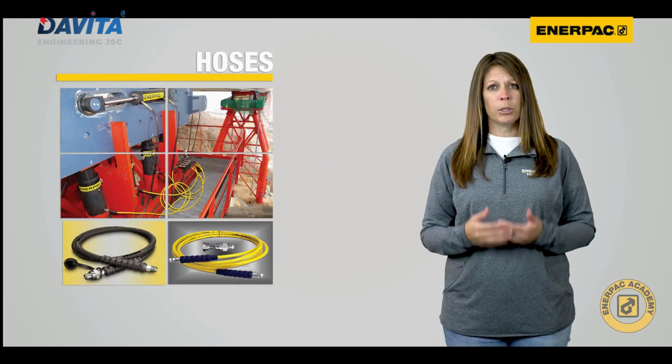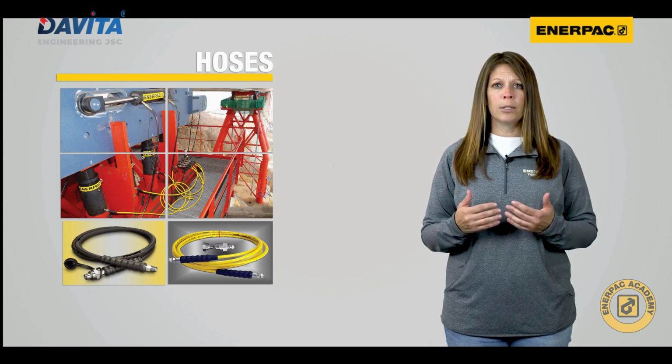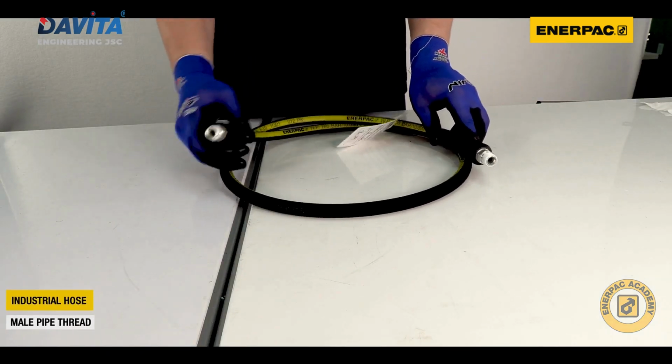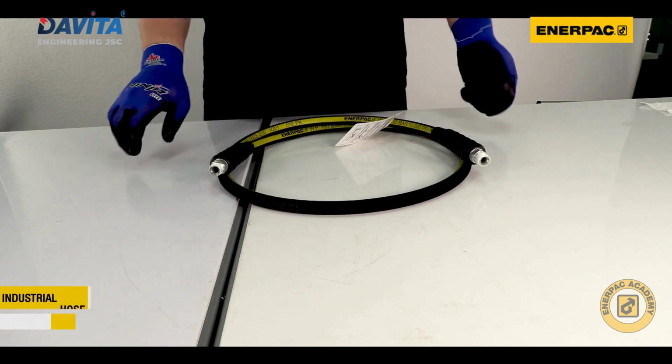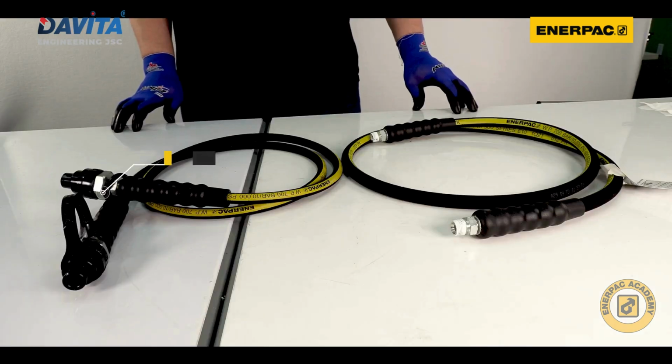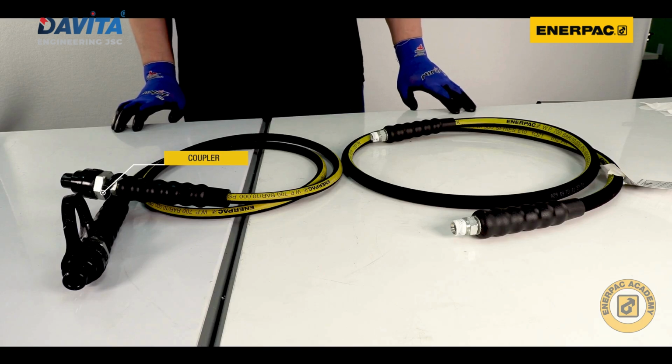The final term to understand is the hose end or end assembly. Most industrial hoses feature male pipe threads on each end. These threads are usually 1/4 inch or 3/8 inch NPTF threads. To simplify ordering, many hoses can be ordered with an installed coupler on one or both ends.